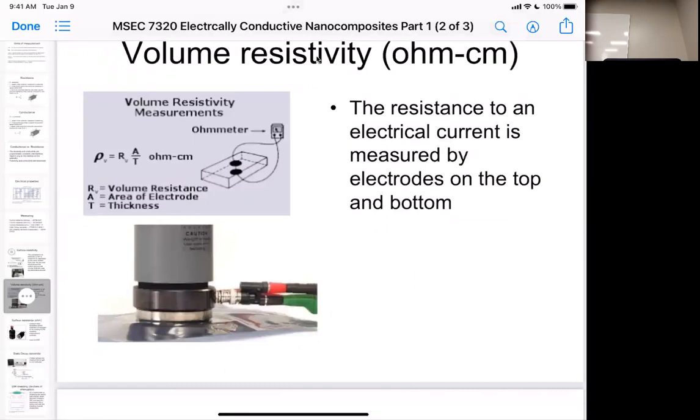And that's actually an interesting problem, because let's say you have a really soft silicone and you don't put a weight on it, and you have X conductivity. If you do put weight on it, it now has a greater conductivity, because you've squeezed all those pathways closer together because of the compliance of the material. They probably have a special setup for silicones, but I know it's a standard weight for all plastics.